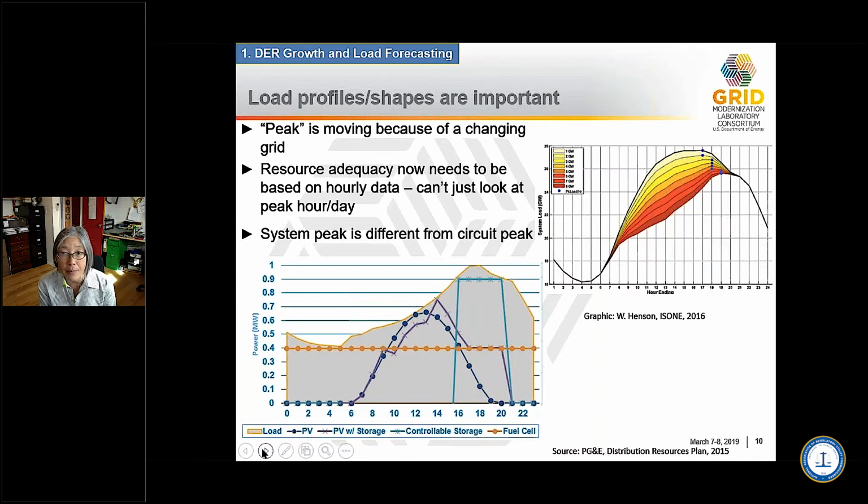Carrie, if you go to the next slide, these arrows are pointing to different points in this graphic. The first arrow shows, let's say I've got a distributed generator like a small hydro plant, which operates 24/7. I'm constrained by that minimum load. It can only be up to 0.4 megawatts. So I've got PV, I'm constrained by that next point where the blue hits the load line, and we can accommodate 0.65 megawatts of PV.